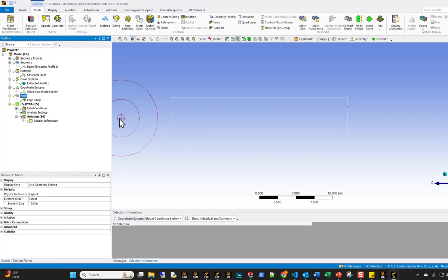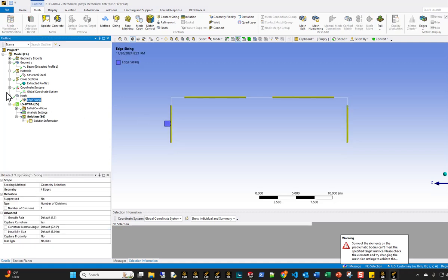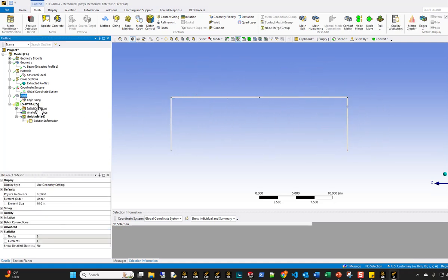This way, I'll create 4 different beam elements in here, right? So as you can see, I now have a total of 4 elements in the model. Elements 1, 2, 3, and 4, each of them has a division of 1. Then we ensure we have 4 different beam elements in here.